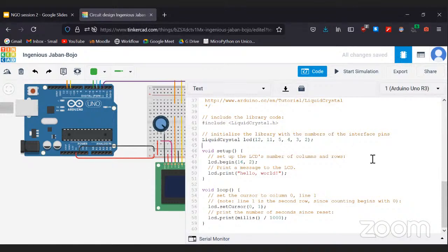And as you can see, the next statement is LiquidCrystal lcd. What the statement is doing is that we cannot just start without initializing the LCD, or telling LiquidCrystal.h that there is an LCD display in our circuit. We cannot go ahead and manipulate it. So we're creating something called an object. The object name over here is given as lcd, but it's essentially like a variable name. You can keep it to whatever you like. Over here, they've named the object lcd, and in the parentheses, they've given you the pins where you connect your register select, your enable pin, and then your data pins.